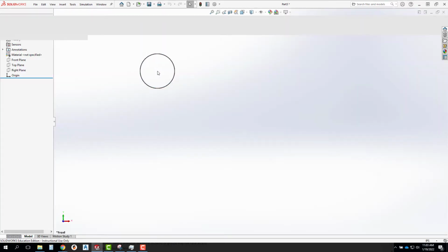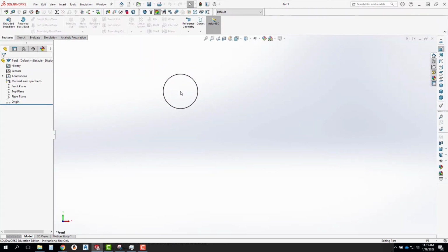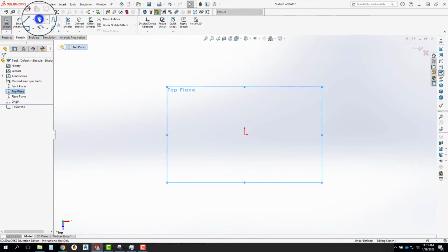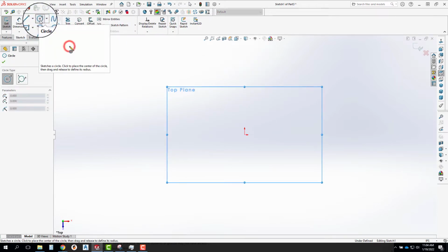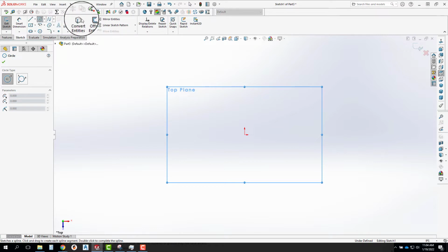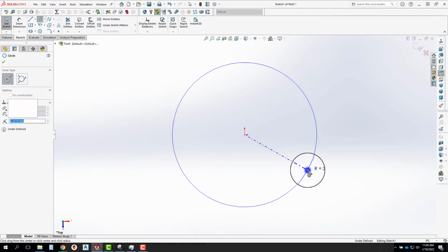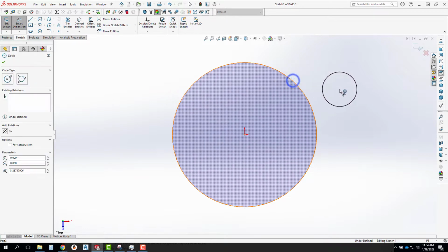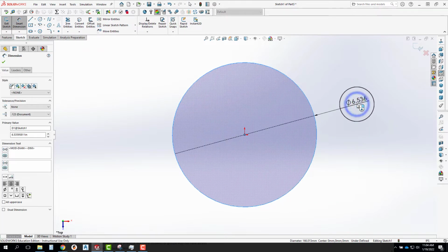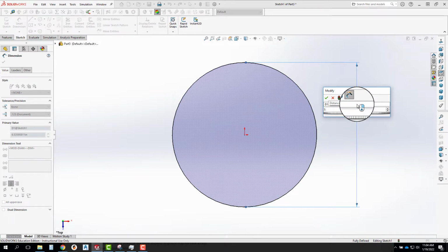The first way I'll do it is to create the muffin tin cup as a solid block shape with the outer taper and then shell it out. So I'm going to start on my top plane. I'm going to sketch, looks like the inner diameter of the muffin cup at the top is 3 inches and the wall is 50 thousandths. So the outer dimension would be 3 inches plus 50 thousandths times 2. So that would be 3.1 inches.